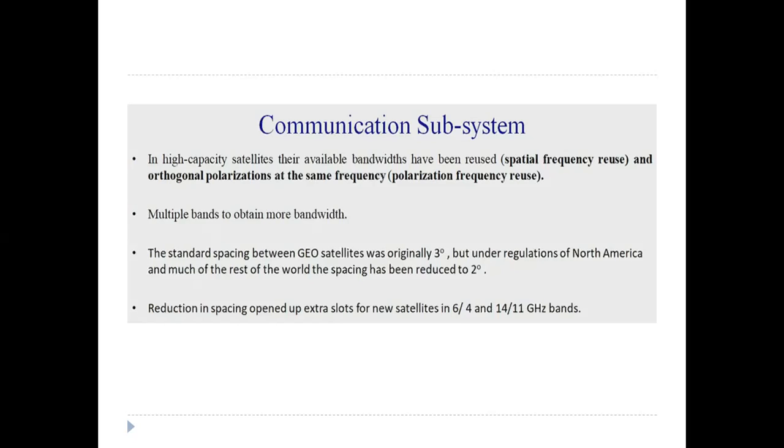Originally, this band had 3 GHz bandwidth allocated to the satellite services, but part of the band was reallocated to the Local Multipoint Distribution Service (LMDS). Approximately 2 GHz of bandwidth is still available for satellite systems at Ka-band on an exclusive or shared basis, which is equal to the combined allocation of C and Ku bands.